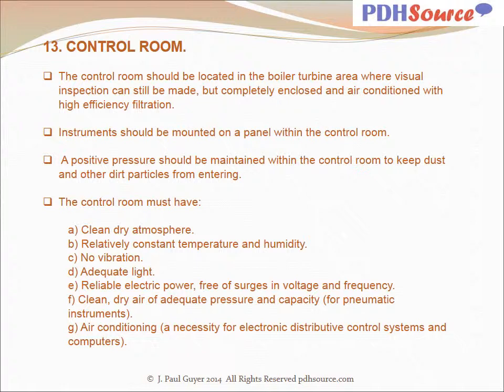With regard to the control room, it should be located in the boiler turbine area where visual inspection can still be made, but completely enclosed and air-conditioned with high efficiency filtration. Instruments should be mounted on a panel within the control room. A positive pressure should be maintained within the control room to keep dust and other dirt particles from entering.